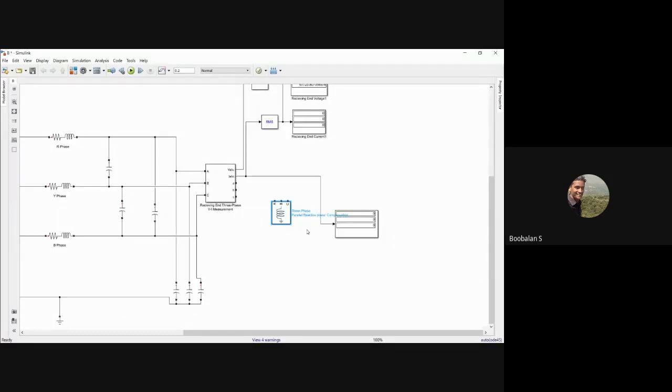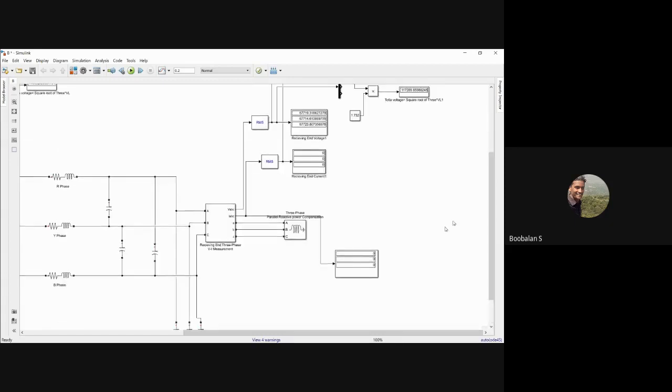By using this, I'm just going to rotate it one second in such a way that you could easily connect it, right? Right, I just connected my three-phase compensation load over here. Now you could verify that my Ferranti effect is getting removed. Now I'm just going to remove this current value over here, right? Now you could see the Ferranti effect is getting eliminated, because I just added a reactive power compensation over here, right?